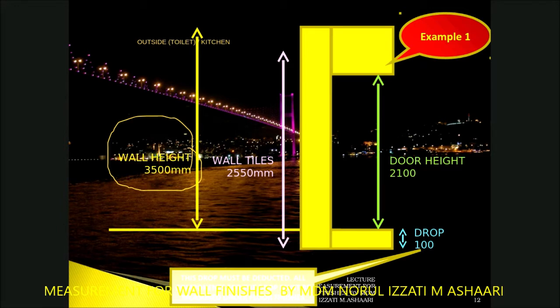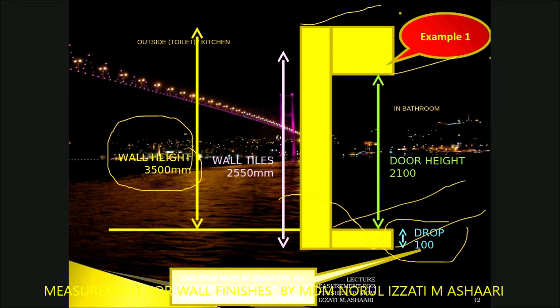So when you go inside the bathroom, normally you have to drop, isn't it? When you have to drop, you have to consider this drop to be used as the reference for you to get the height. In order for you to get the height of the wall finishes, you have to consider the drop. This drop area must be deducted. Let's say you want to measure the area. You need to take the length on plan, right? You have to take the length on plan and you have to consider the height.